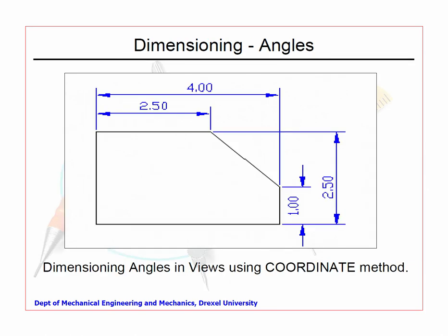Next we come to how to mention angular dimensions. These angular dimensions are required depending on the particular type of job that we require. Sometimes, for example, this looks like a chamfer in a corner, or it could be a mating part. What they have written is the remaining portion, after you remove that, the remaining portion is mentioned here.